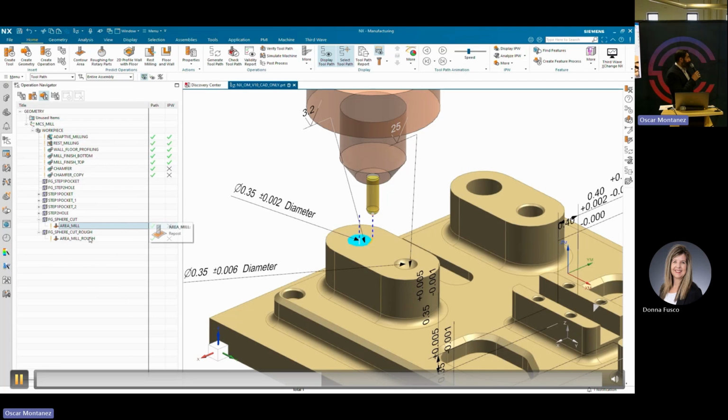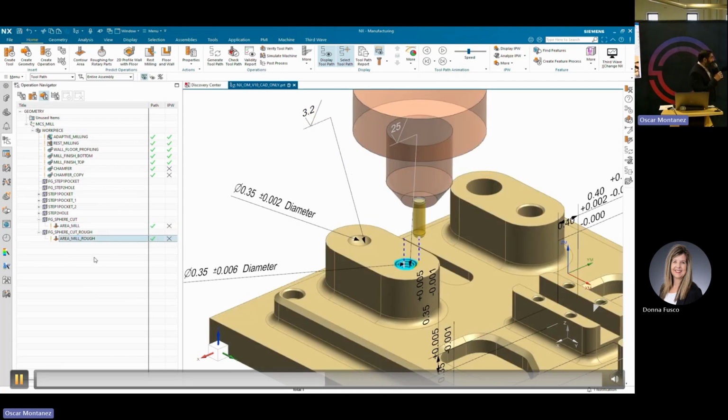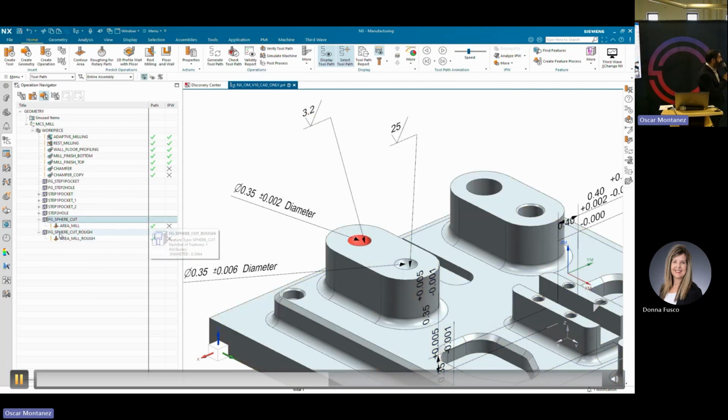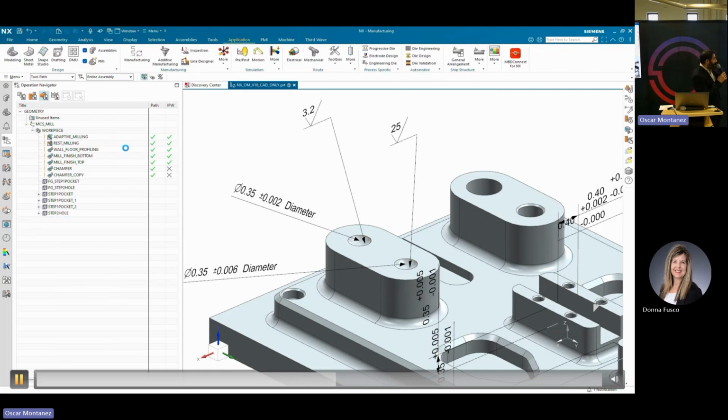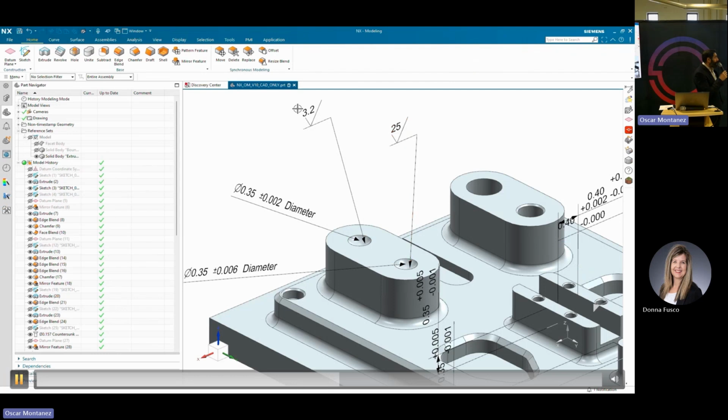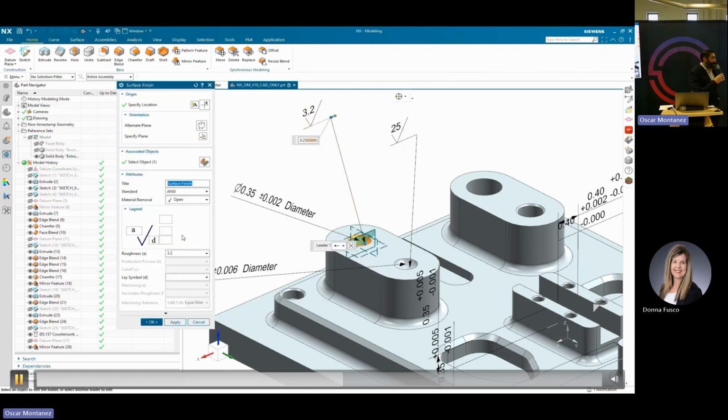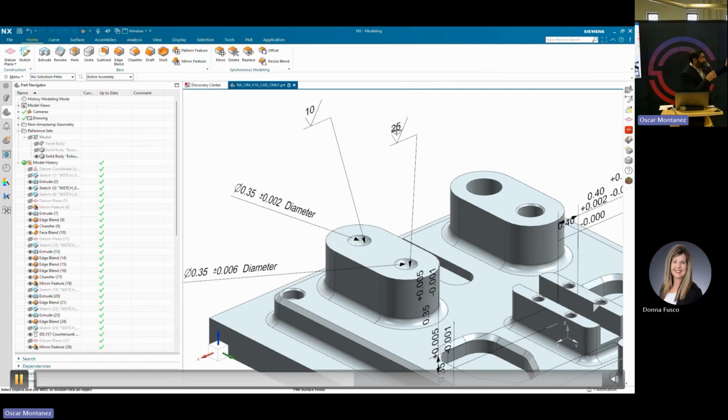So there, when we actually visualize it, you can see that for the smoother surface finish requirement, you have a smaller step over in the helix. If you have a rougher surface finish requirement, the helix step over is now greater. What I'm doing now is I'm gonna do the same thing.